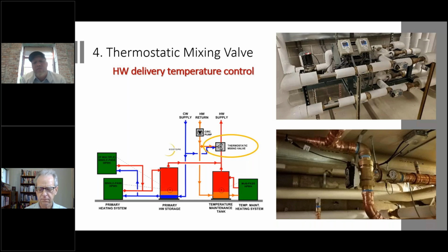The other part that's really important is making sure you're sizing that thermostatic mixing valve properly. We do a lot of commissioning of other projects, and oversized mixing valves are definitely a top 5 issue that we've seen and had to address. They have a sweet spot in the range, and you size those based on the recirc load plus your peak loads, and then you need to make sure that those are selected properly.